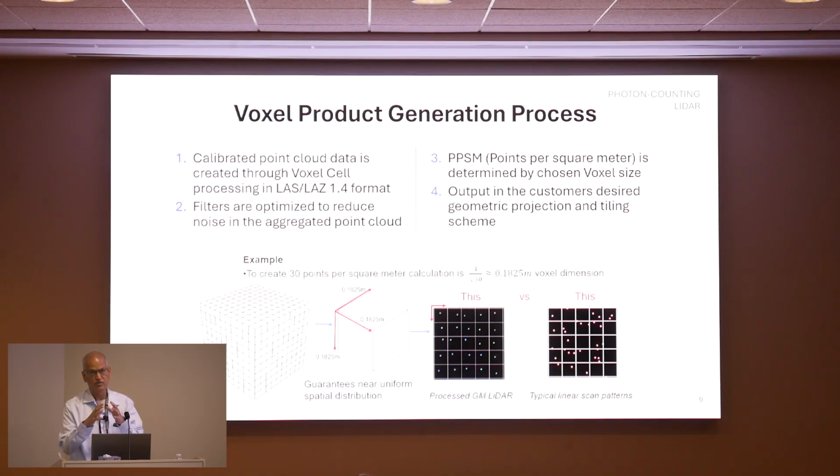Only at the time of data collection, up to this stage, the linear mode LiDAR and the Avalanche LiDAR will be different. Once you do the voxel processing, you will be given a LAS file that is exactly the same as the LAS file you create from the linear mode LiDAR. If you already have a workflow established using standard software, you can take your LAS file and process it in the same way. After that, there is no distinction between a linear mode LiDAR or an Avalanche LiDAR. The only thing is it will have more points.